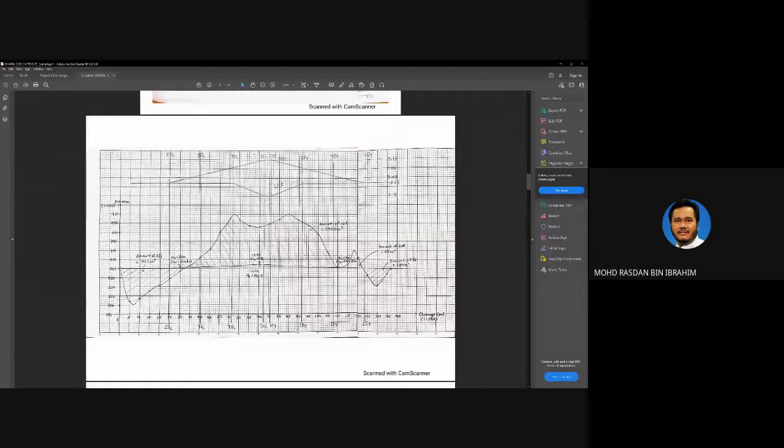If you go from here straight to the top of this hill here, let's say 100 meter over here, from here go straight down. The difference between the highest point and the starting point divided with the length is going to be your gradient. It's going to be more than 10%. Maybe 50% in this case.